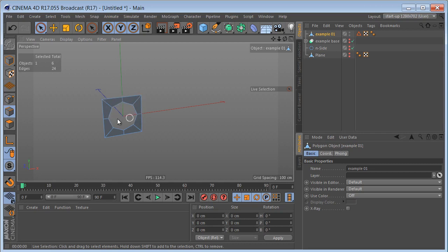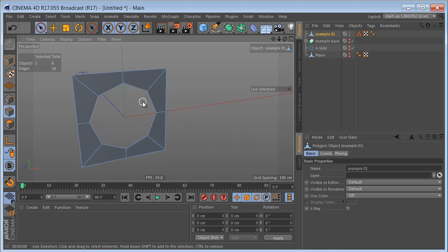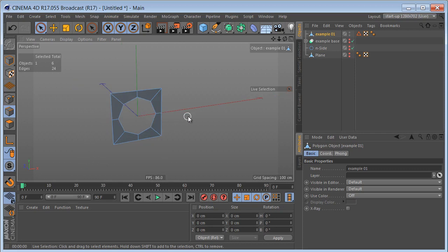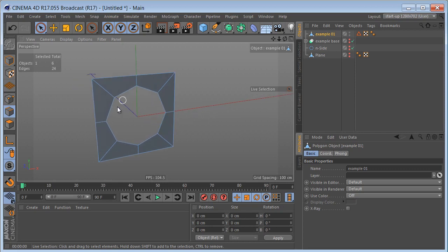It's going to be 160 of these holes around that final object. And you don't want to create control edges and depth for each of 160 holes separately. So we have to finish this object, and then we can copy it around and wrap it around a circle spline.